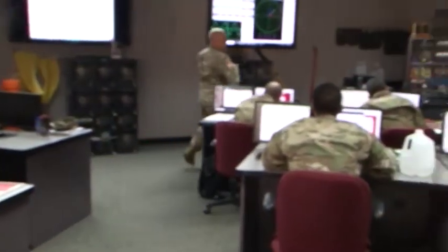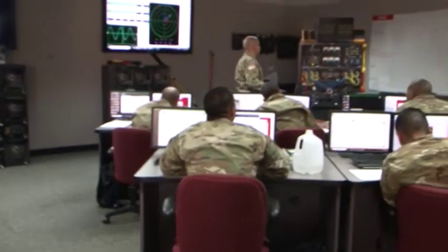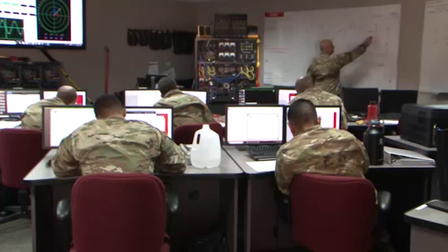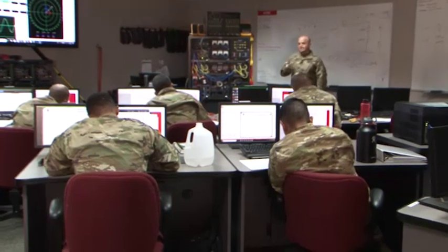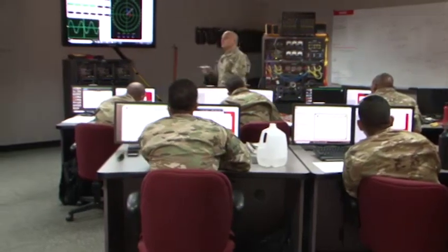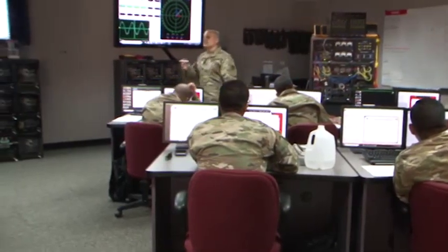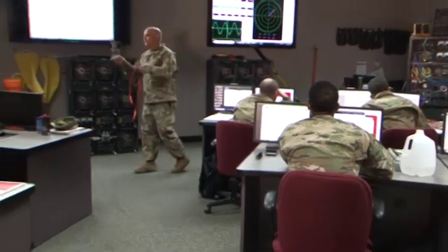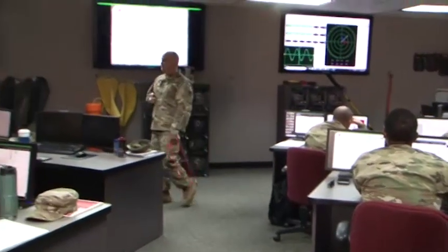It's just a series circuit, and when I say series circuit, it's because you're going to be setting up some various ones today. This is one right here. This is an example. That might even be the same values. When you solve for the impedance of it, you're just going to be using Z equals the square root of R squared plus the resultant of whatever your reactances is squared.